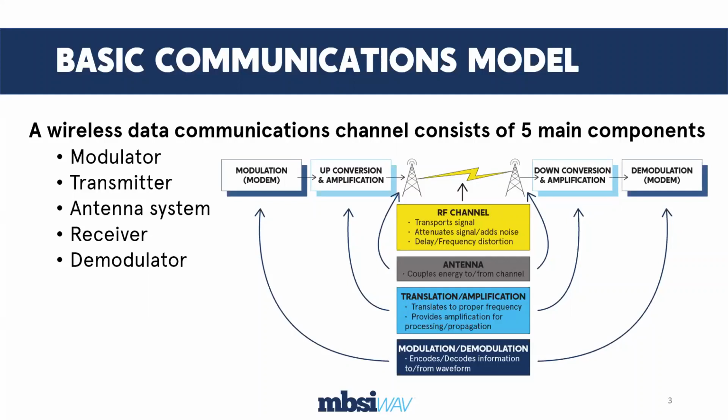And then somewhere out there, there's a CPE device or a subscriber module of some sort that is going to receive that and take the signal, convert it down into something that can be demodulated, and then handed back out to the Ethernet port again, and the data is received. Then exactly the opposite happens in the other direction when we're going from the CPE device up to the transmitter. It's exactly this process, just turned around, that's all. So we modulate, we up convert, we transmit, we receive, we down convert, and then we demodulate.